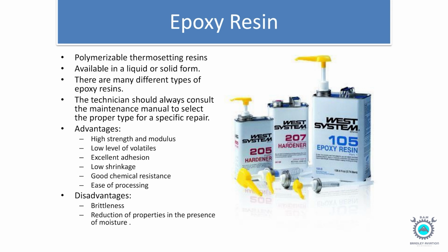Epoxy resin. Polymerizable thermosetting resins, available in a liquid or solid form. There are many different types of epoxy resins. The technician should always consult the maintenance manual to select the proper type for a specific repair. Advantages: high strength and modulus, low level of volatiles, excellent adhesion, low shrinkage, good chemical resistance, ease of processing. Disadvantages: brittleness, reduction of properties in the presence of moisture.